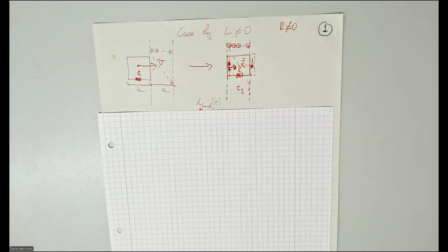Remember, before I told you the example which we are doing now is for L equals 0, or equivalently for current equals 0. But current equals 0 is quite abstract, because we don't have current equals 0 in our example. But we can consider L equals 0 in the sense that it is very small, negligible, but basically in the motor it is never negligible, because the inductance plays an important role in the magnetic flux, and in the current.